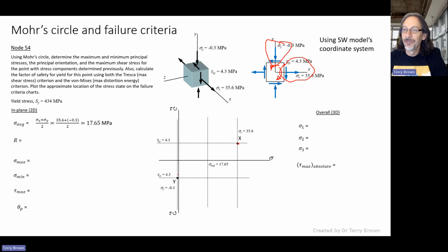Now we've just got 2 points. Draw a line between them where it crosses the horizontal axis. Because we're the same distance above and below, that's going to cross at the middle of the line. That's going to be the center of the circle. The line from here to here is the radius. We've got a little triangle here that we can use for Pythagoras to do our calculations.